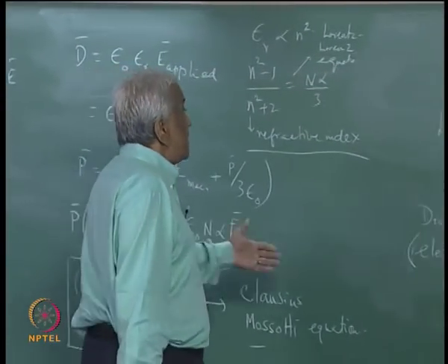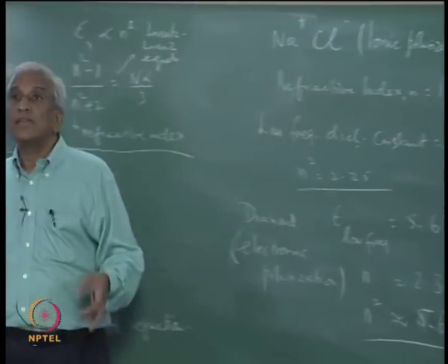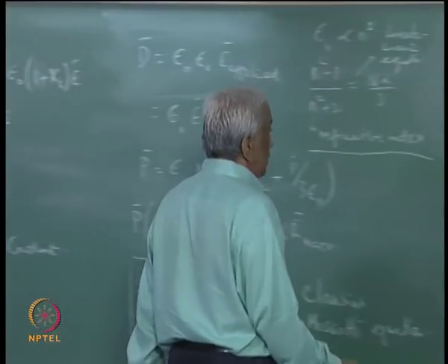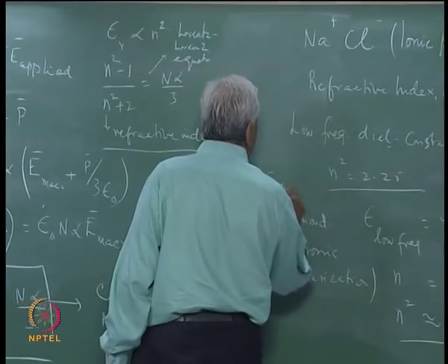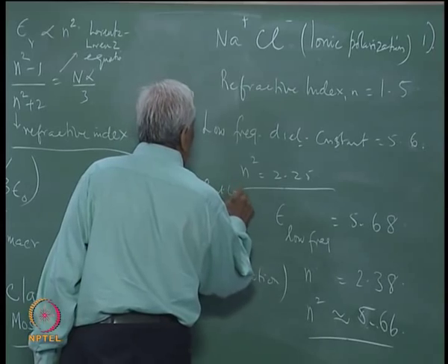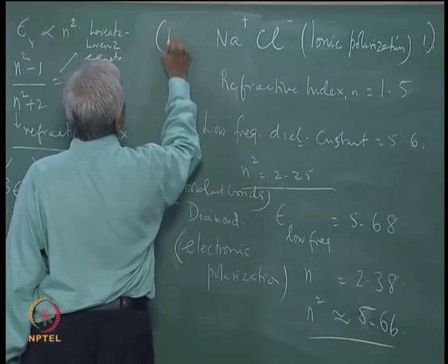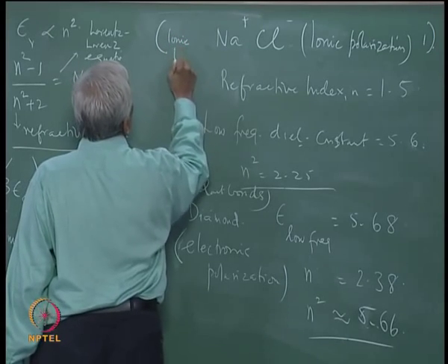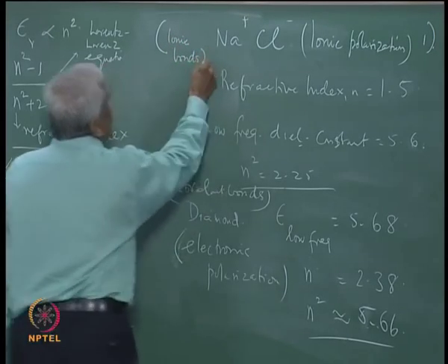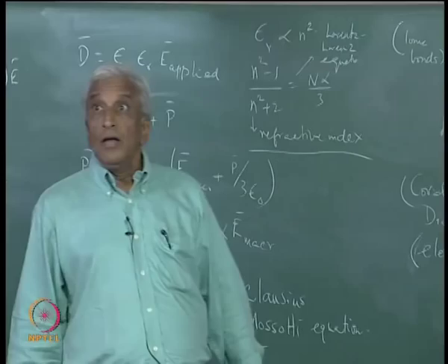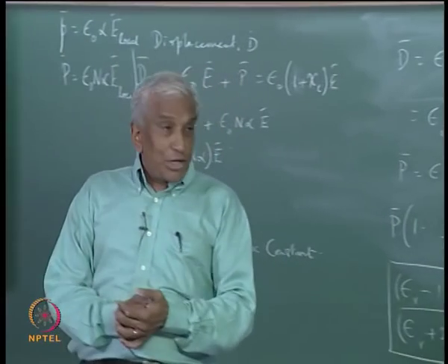In the case of diamond, it is exclusively electronic polarization. There are no ions there, it is a covalent solid with covalent bonds, whereas here these are ionic bonds. So, when there are covalent bonds, it is only the electronic polarization which contributes to the dielectric polarization, and hence the dielectric constant. When you consider a material like water,